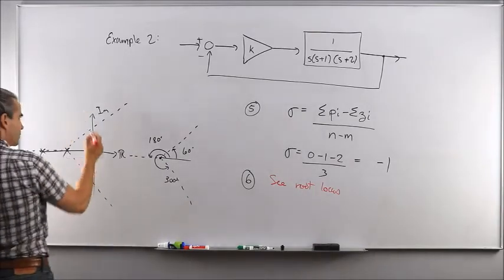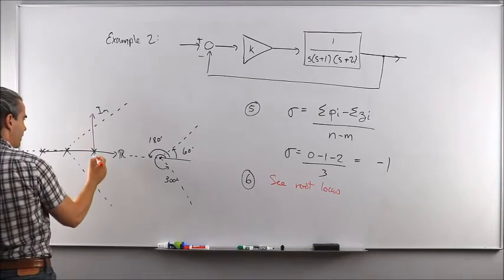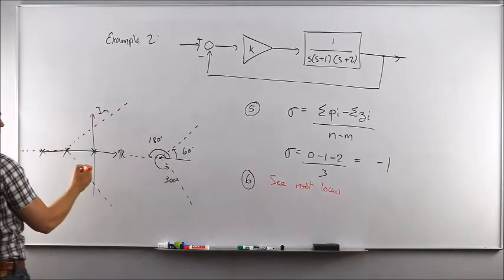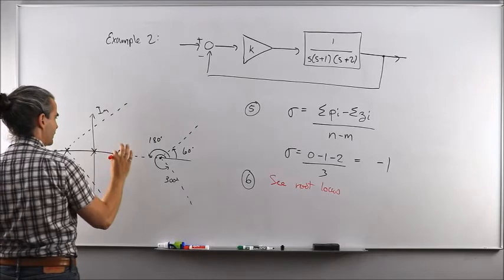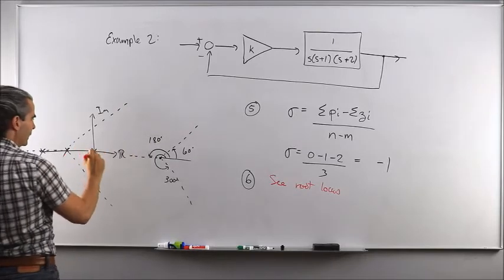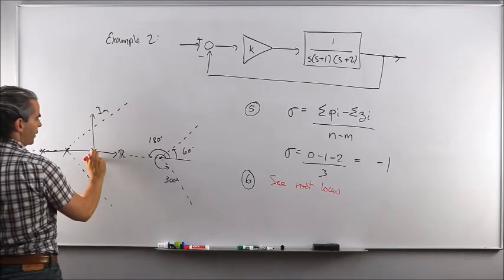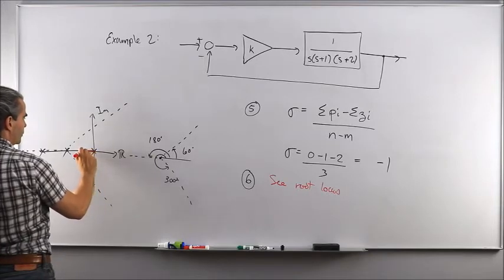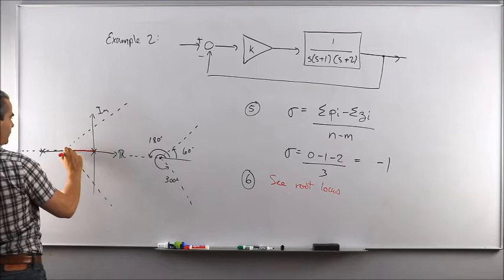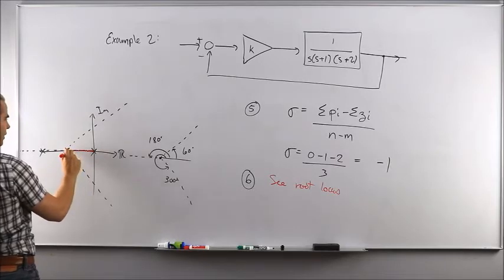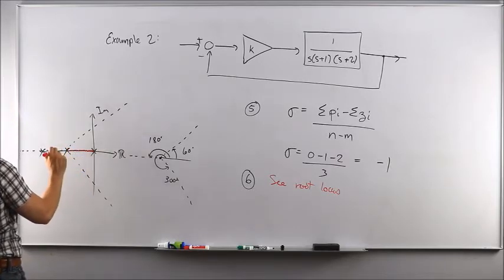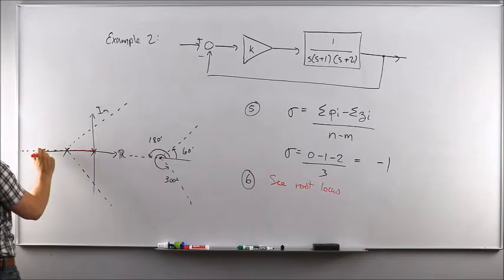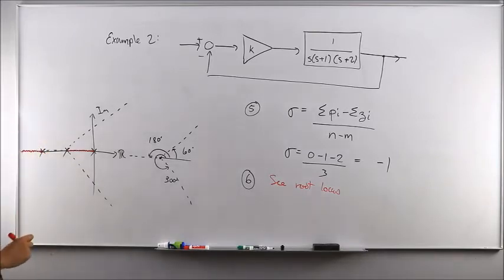Okay? So starting at the imaginary axis, counting towards the left, whenever it is odd, pen down; even, pen up. I'm starting, there's already a 1. This is an odd number, so pen down. Boom, boom, boom. Oh, this is the second object I encounter, pen up. 2, 2, 2, 2. Oh, third one, pen down, all the way to minus infinity.